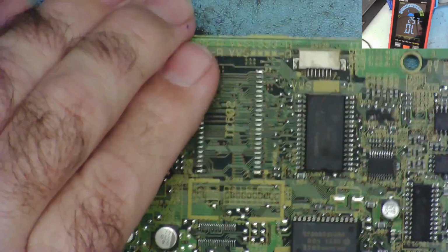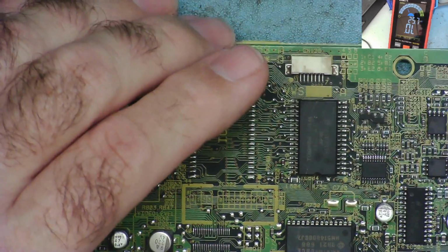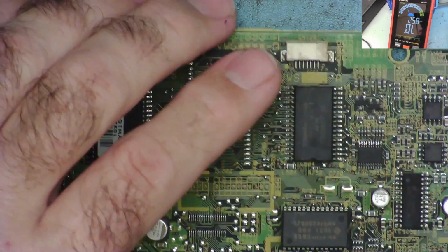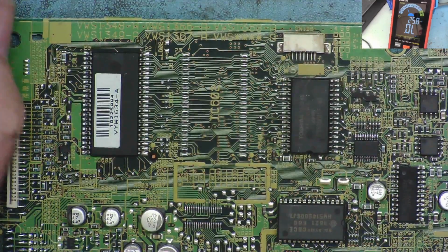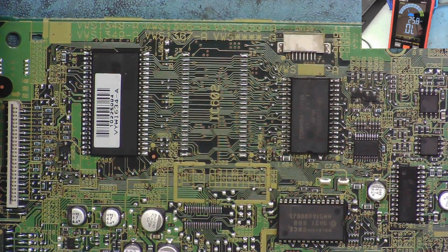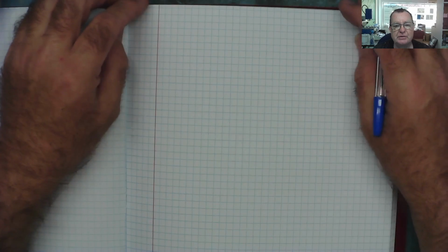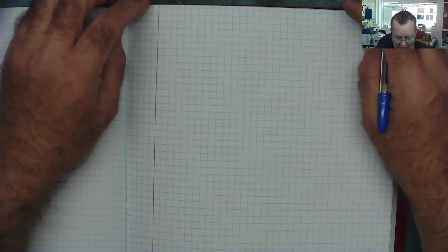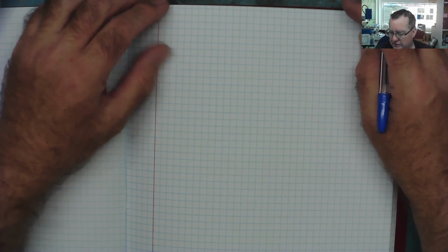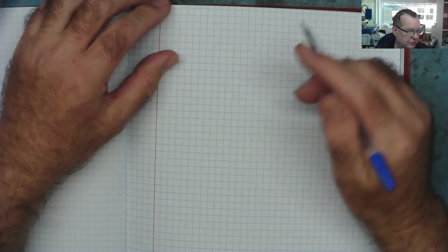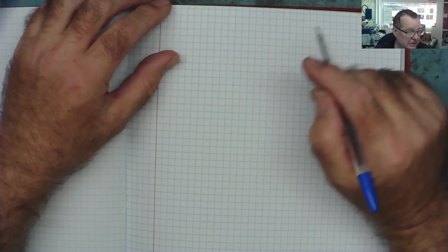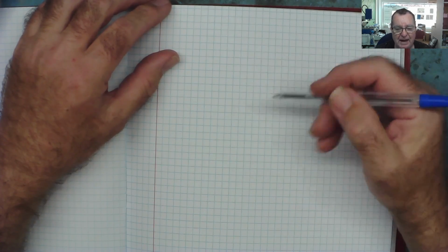So you can test transistors in circuit. I've shown you 2 examples, but it'll probably only reliably find short circuit transistors for you. We can see that testing transistors in circuits can be problematic. You can normally spot a short circuit transistor or short circuit junction. Occasionally in circuit, even that will let you down.